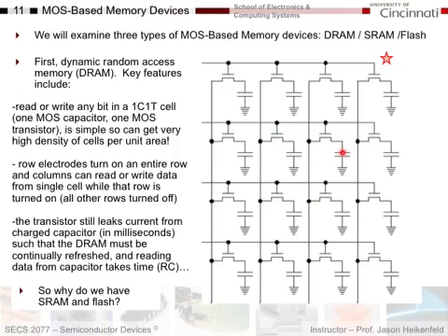As soon as I'm done with that, I will turn the voltage off to these transistors, and then the storage on this capacitor is isolated from the line. So this goes off, and I can keep the charge on the capacitor. If I want to write all the memory, I'll do the first row, turn these all on, send all the data up to the capacitors. I'll do the second row, the third row, the fourth row, each row one at a time, writing the data through the transistors to the capacitors.